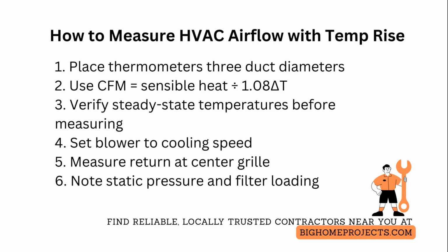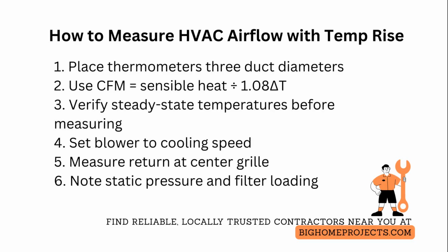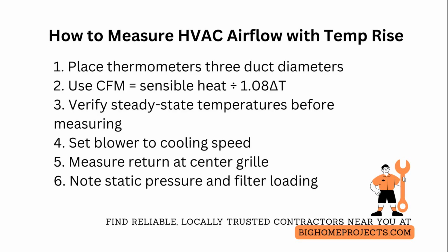Use the formula CFM equals the sensible heat output in British thermal units per hour divided by 1.08 times the temperature rise. And when working with gas furnaces, confirm the declared steady-state input and rated efficiency to compute true sensible heat rather than relying on nameplate values.